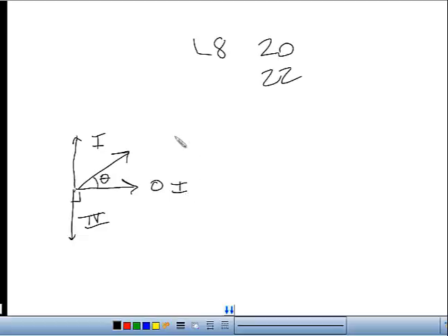We're going to use our mnemonic device of Eli the Iceman, and we'll know that all of our inductive vectors in a series circuit will be positive angles, and our capacitive displacements will be defined as a negative angle. Of course, if this is a negative 30-degree displacement on a capacitive RC circuit, you could also call it positive 330, but let's just keep it simple and use the included angle. Just remember that it's a negative angle.